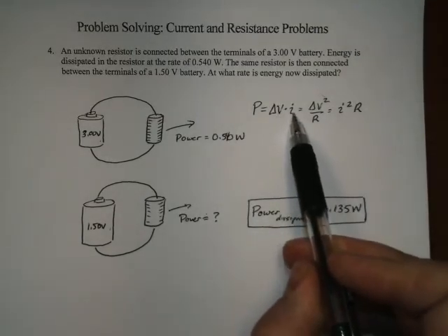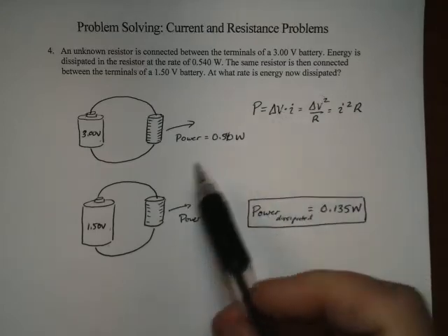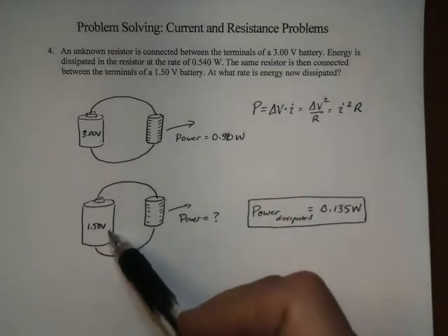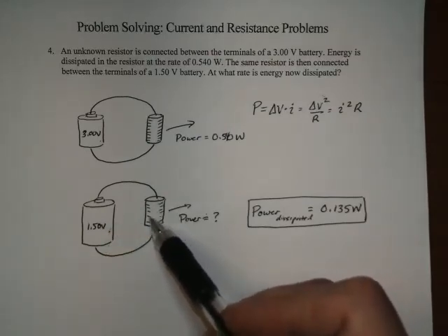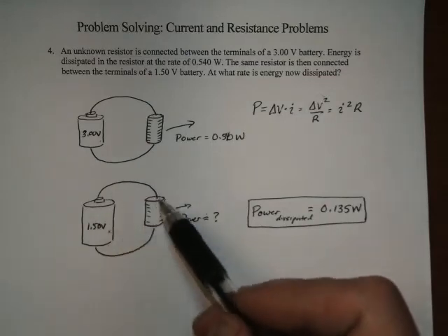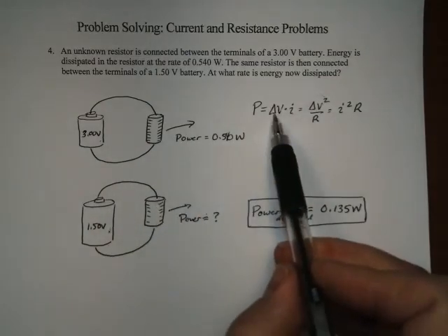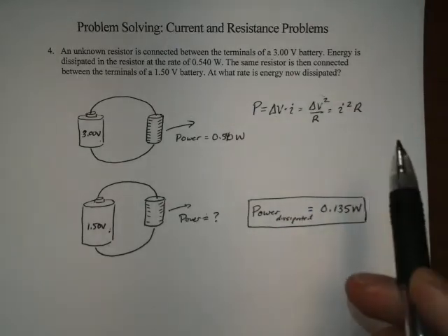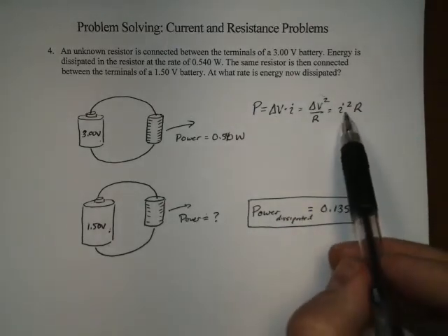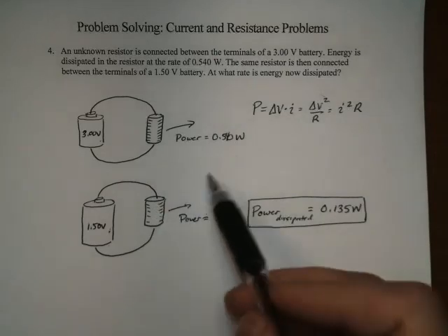But there are other ways you can come to that similar conclusion. Take, for example, this first one, voltage times current. Well, we already know that we've cut the voltage in half. But Ohm's law would also tell us if you cut the voltage in half across the same resistor, you are going to cut the current in half that's going to flow through that circuit as well. So half the voltage, half the current, again, predicts 1/4 of the power. Or this one, I cut the current in half.